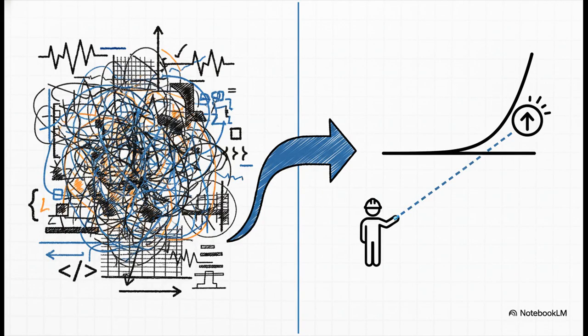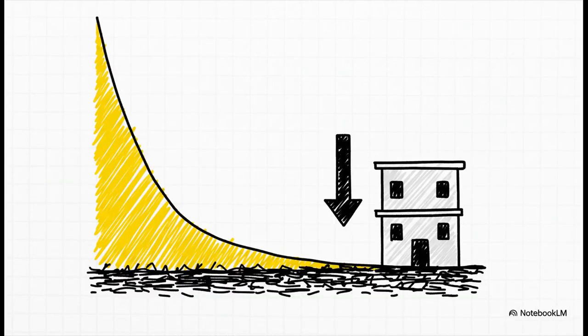And this is where the genius comes in. Instead of running thousands of super complex simulations for every new building, an engineer can just look at this curve. They figure out their building's natural period, they find that spot on the chart, and boom, it tells them the peak force they need to design for. It's an incredible shortcut that boils down decades of seismic data into one powerful tool.